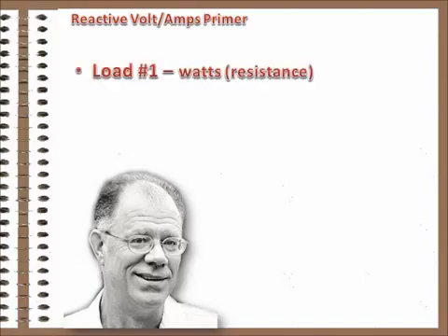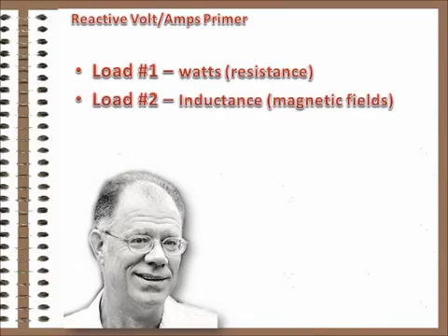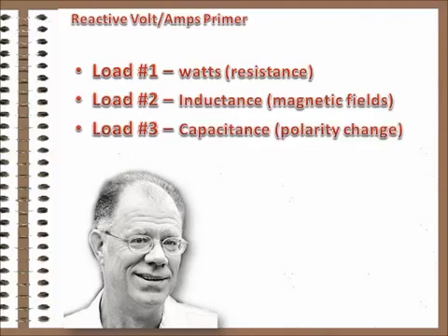Aside from the watts used in your circuits, there are two other types of load: inductive from the magnetic fields and capacitive from the changing polarity in all AC circuits. These extra loads use capacity, heat up lines, and cause other problems. Your power supplier takes various steps to handle them, but they're a fact of life for your electrical system.